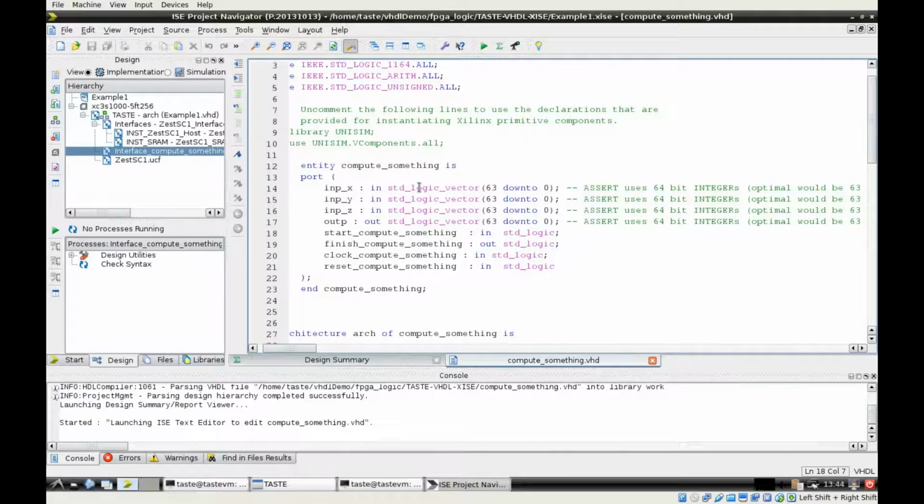in addition to what you see here, for the FPGA there will also be a driver generated completely automatically based on your design, based on your specification, on the model that you're using. And what this driver will do, we will see it actually soon in the code that will be generated. It will map all the input parameter values into these input signals, and as soon as it does this and writes to the appropriate registers to populate this information inside the FPGA, it will then raise this flag, it will raise this bit, and the FPGA state machine waits